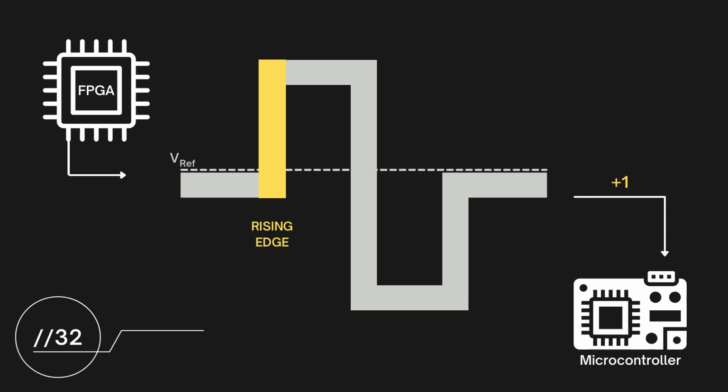When the 1 second period is lapsed, the microcontroller transmits the number of rising edges back to the host CPU, relaxes the interrupt handler, and waits for further commands. Now that we've established the mechanisms, let's look at our parameters.